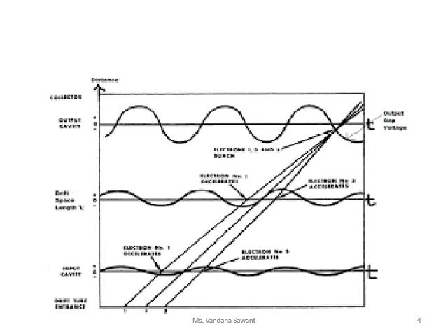Here, if we compare the reflex klystron and the two cavity klystron, instead of a single cavity, two cavities are used. Both the cavities are kept at a far distance from each other. Both are reentrant cavities, and they are kept vertical, not horizontal as in a reflex klystron. And the electrons which are emitted by a cathode will form the beam with the help of an axial magnetic field.